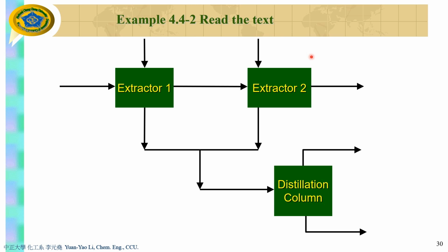Okay, so let's go to the next page, page 98. The acetone solute, water is dilute, right? The mixture is firstly contacted with the MIBK solvent in a mixer that provides good contact between two liquid phases. A portion of the acetone in the feed transfers from the aqueous phase to the organic phase in this step.